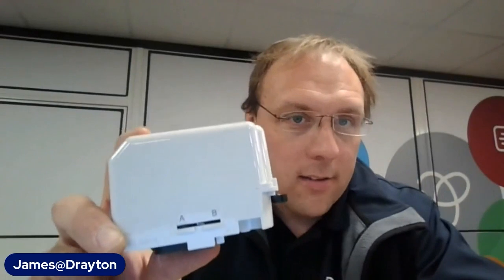We also do the ZA6, and that tends to come with the 28mm bodies. That's got an extra wire on it, an extra white wire, which is just a normally closed position. So what you can do with that is, if you want the valve as it is now, if we energize the valve open, so we move it from A to B, we make the little contact inside, and that sends the signal off to fire the boiler.